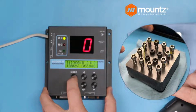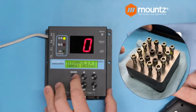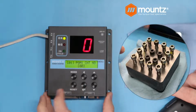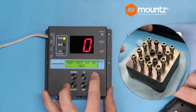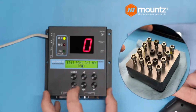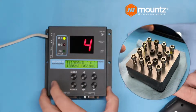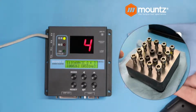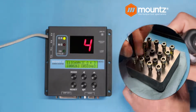Then we can go back to our work, and let's program the number of fasteners that we are using. To do that, I can go into our parameter section, and the first parameter is the count for number 1. So let's set that to 4. Save that, and now we can come back into our operation mode, and we can now run 4 fasteners down, and we can see if those are going to be accepted or not.